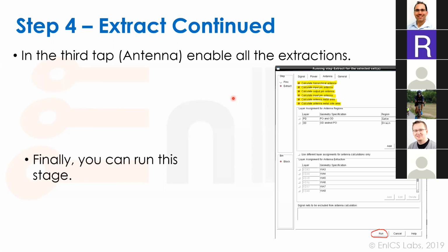But in the place and route tool, could be a different assignment in terms of vertical versus horizontal routing tracks. So the tool might think that it favors metal 2 to be horizontal, but metal 4 should be horizontal too, because it's all usually HV, like interleaved. So if you assign it incorrectly, the tool will try to route to it with its horizontal attributes when it's actually vertical in your layout, okay? So it's better to sync on the used layers.